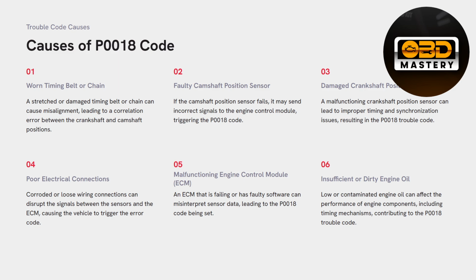Poor electrical connections: you're going to want to inspect the electrical connections and make sure that they're not corroded or loose. Malfunctioning ECM, which is really rare, but it's never zero. You could have a failing ECM or faulty software that could just start sending these codes out of nowhere.